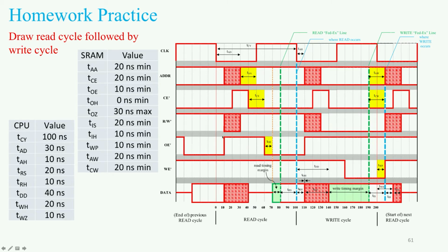And so then that is high for this period of time. We can safely think about that as being high because this clock signal is always going to be low. So the read-write bit can flip around and do all kinds of crazy stuff, and it doesn't matter, because as long as the clock is low, the output enable signal is going to be high. If you look back at that logic.